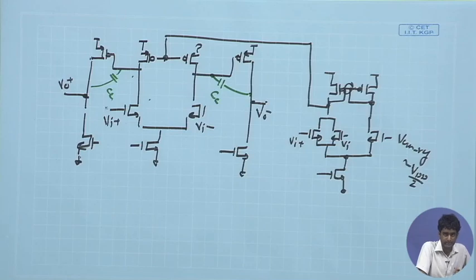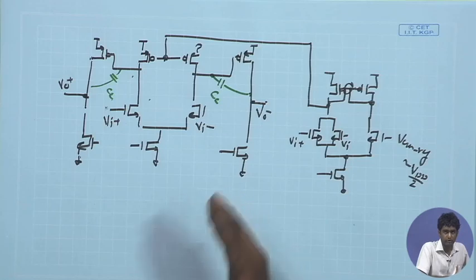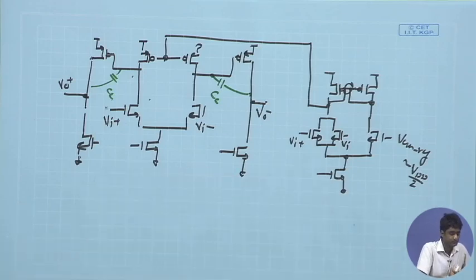That is what we discussed last time, and therefore we explored the alternative where we can have two isolated loops, two different loops. And then we just now discussed the transistor level implementation of both the loops and the stability considerations, looking at the conflict between the two loops and making sure that the stability analysis of one of them is not influenced by the other. So, this is an important conclusion that we just arrived at.